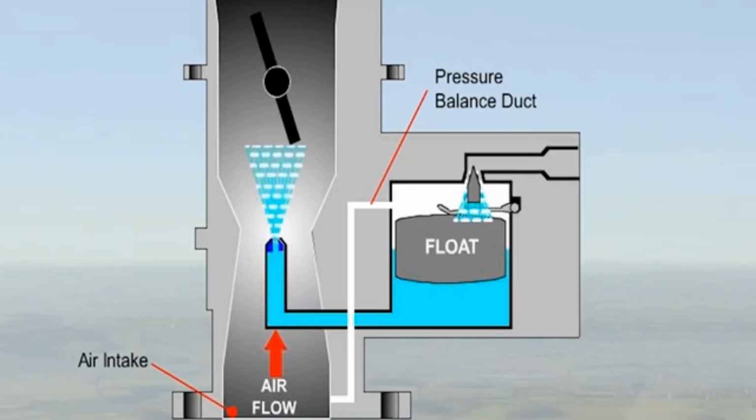As engine speed and airflow through the Venturi increase, the proportion of fuel to air rises as a result of the different flow characteristics of the two fluids. This causes the mixture to become richer as the engine RPM increases. In some ways, this may be looked upon as serendipitous. After all, at high engine power, we need a rich mixture. However, this is a bit hit and miss, and it doesn't allow any accuracy in setting the mixture.